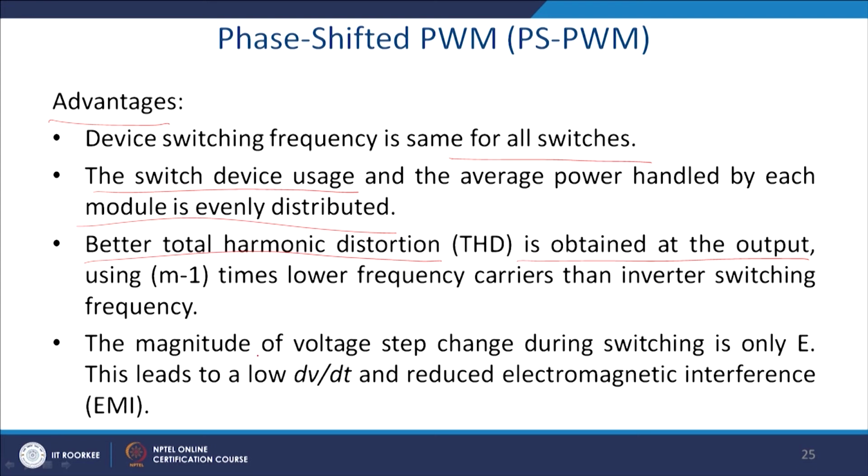The magnitude of the voltage step change during switching is only E. This leads to low dv/dt and reduces the electromagnetic interference. So, these are the major advantages.